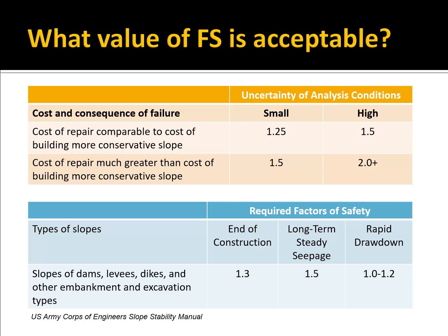For a given project, there are different scenarios that you run. For example, for a dam or levee, they do an end of construction slope stability analysis where you use unconsolidated undrained strength parameters. And then for long-term steady-state seepage, you do an effective stress analysis with the pore pressures with a piezometric line, where the pore pressure is drawn from a seepage finite element program. And then you'd also consider rapid drawdown. Some point, after a long time after the reservoirs come to equilibrium, you get a rapid drawdown case.